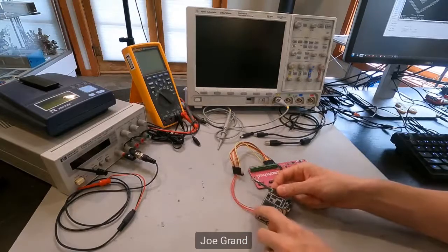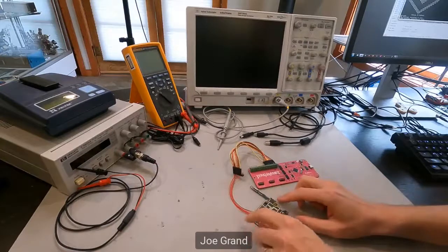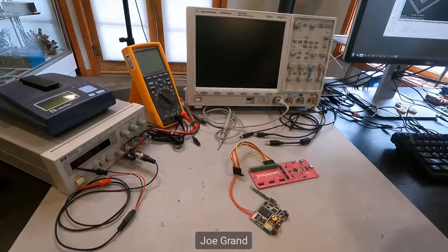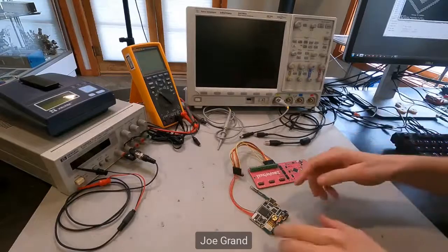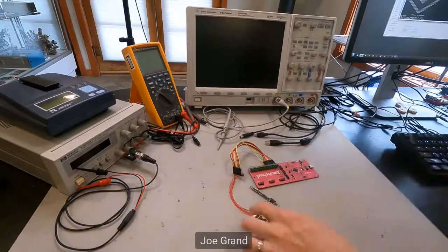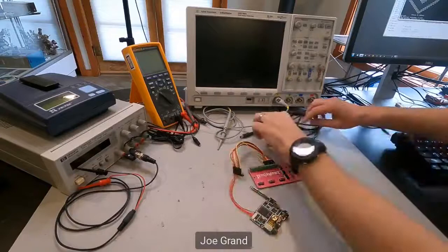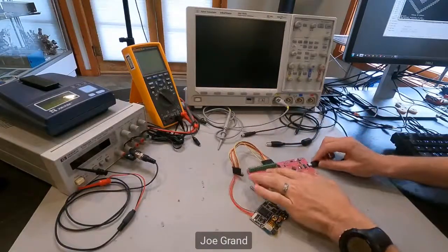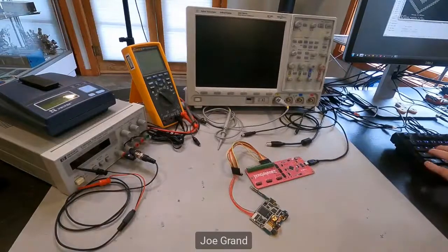There's a little piece of tape here, but there's all these wires. There's like an unpopulated connector right at the edge of the board. That's a good indication that it's, you know, a programming interface or test interface or whatever. So we can tap down onto those and hook up our tool and identify those pins. And then once we identify those pins, we would go to the next step, which will be the next demo.